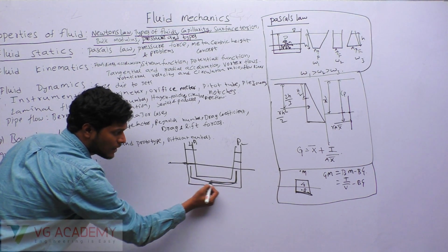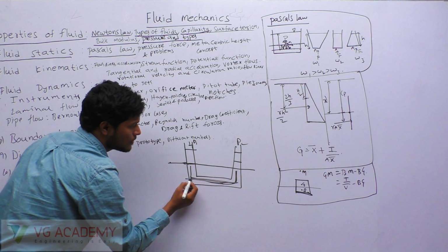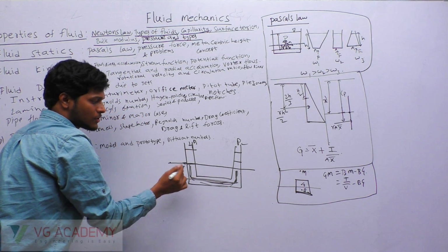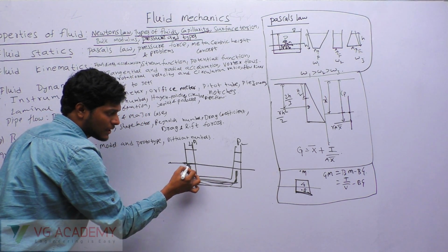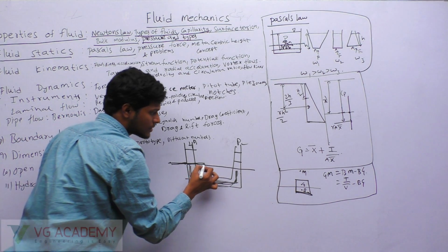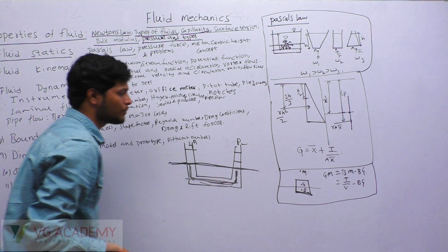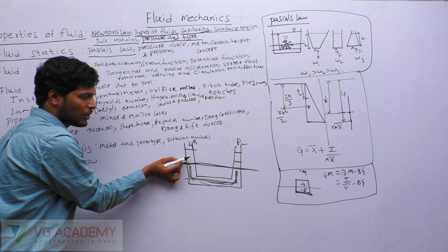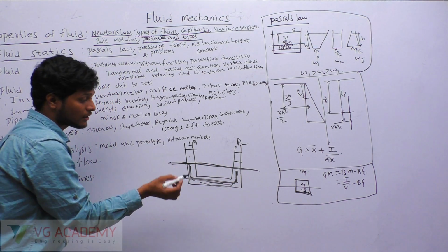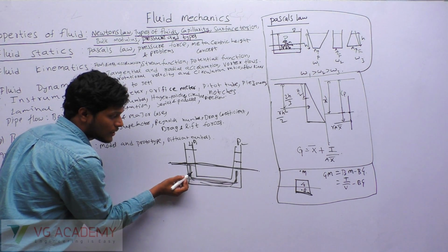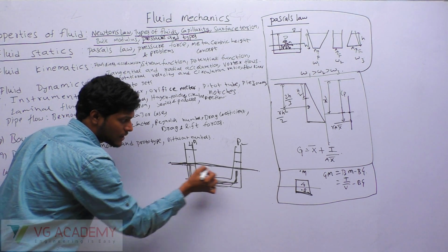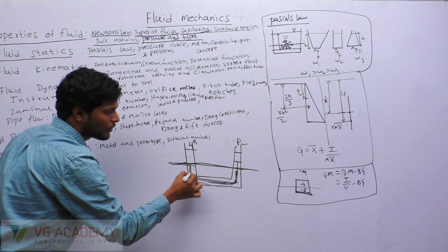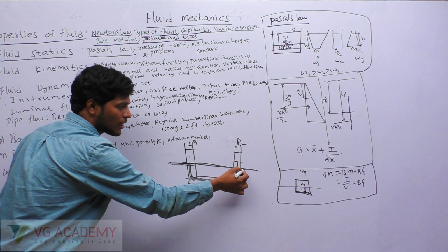Okay, see what the liquid is here. Where this liquid is ending, they will give you the height values. At whichever point they have represented the height at the end, draw a straight line there. Don't draw the straight line here, because if you do, you will meet another liquid. You should not do that. Draw the line here only, so that the line touches the same fluid on both sides. Here entirely you have the same fluid, right? So here only you have to draw this.